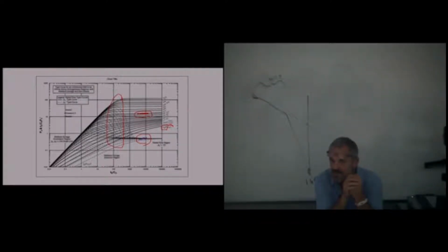But usually the early time region is very messed up. From tests that I looked at, usually the early time region is messed up, and you have to get a really high resolution gauge to get it, especially if you have high permeability. If you have high permeability, you're off to the races right away. The problem in well test analysis is if you have high perm and you hit a boundary right away, you may never have a middle time region.